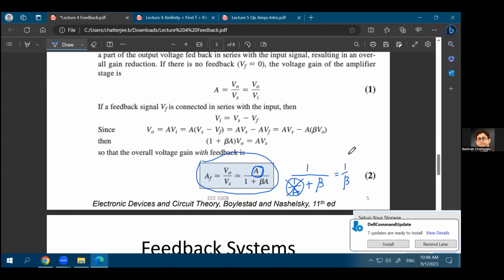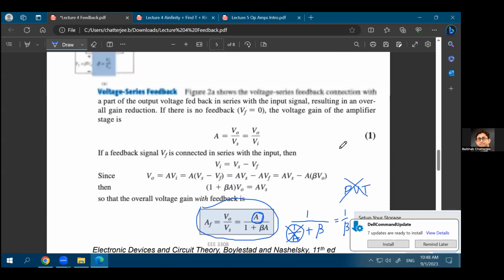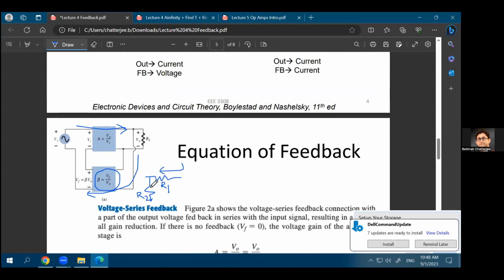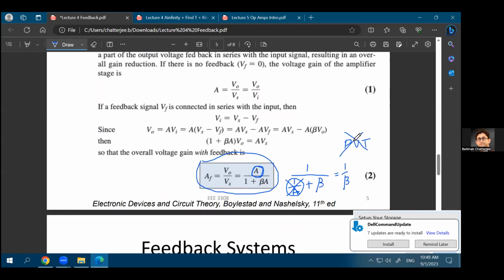But the interesting thing is that this gain is not dependent on your process voltage or temperature. So this is PVT invariant. It is a ratio of resistances. The beta factor is given by a ratio of resistances, and the ratio of resistance is invariant of the voltage. So let's say you had a voltage of 10 millivolt over here. If you have a 10 millivolt versus 100 millivolt at the input, the voltage division ratio will still be same, right? The voltage division ratio does not depend on the input for a resistive divider. So you already see that the effect of V is not there anymore.